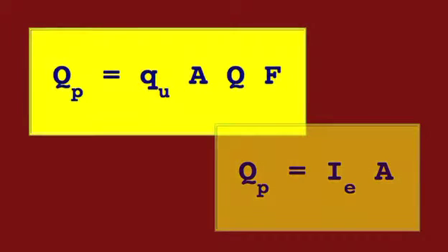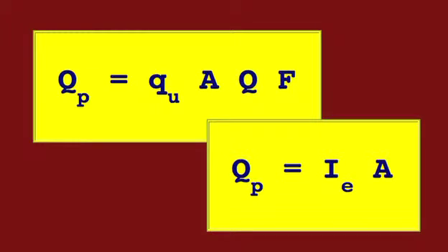In the TR55 method, effective intensity I sub E is replaced by the runoff depth Q associated with the 24-hour storm. The catchment area A is present in both TR55 and rational method formulas. Thus, in TR55, unit peak discharge and, secondarily, surface storage correction factor account for runoff diffusion. Runoff diffusion prevails in mid-sized catchments. Runoff diffusion is not explicitly accounted for in the rational method.